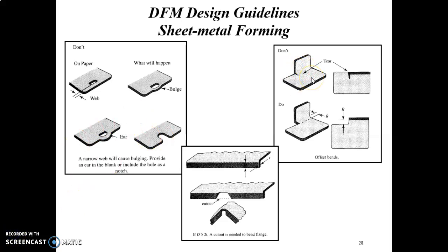For this figure, it illustrates a design that is not desirable for quality or economy. When the form is inside the blank profile, the material must be torn through the stock thickness and the bend radius. If the part is under stress, this step will likely cause fatigue failure. In addition, stock tooling cannot be adapted because the flat area adjacent to the form must be held in position during forming, which means extra tooling expense.